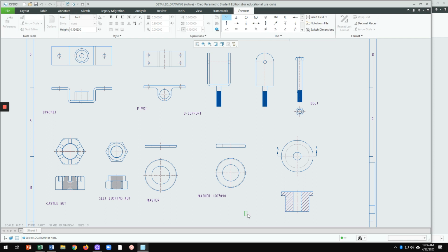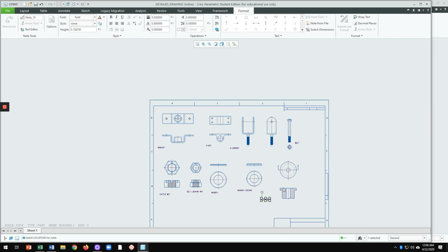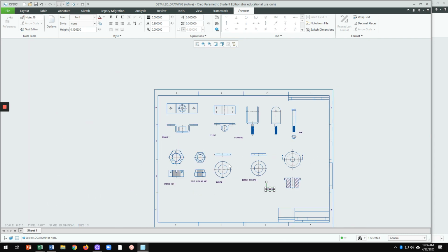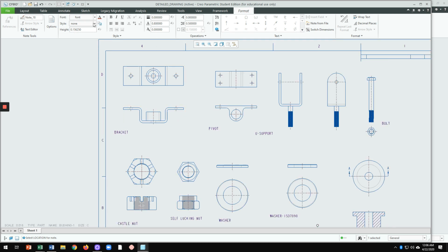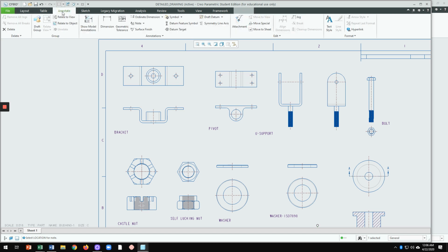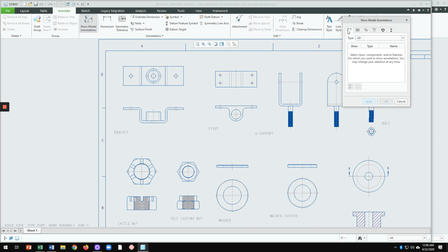Okay, all right. So, and then we say bushing. All right, great. And now that you have all these mechanical drawings for the shock assembly, you can just go and dimension it. And the dimensioning, you can do the manual dimensioning, or you can just do the automatic dimensioning. Just go to this dimension. For example, click inside here.